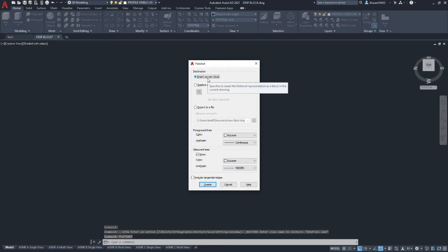Because I plan on just doing a view that shows the plane of the auxiliary view without hidden lines, I'm going to deselect showing obscured items. Now we're going to have to heavily edit this view anyway, so it's your choice. I'm not going to grade it one way or the other, whether you show hidden lines or not. But in my opinion, you're trying to clarify just a detail with an auxiliary view and not clarify visualization of the entire part, especially if it's only going to show a portion of the part.